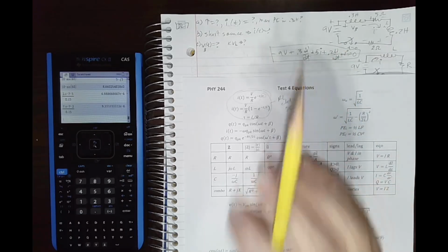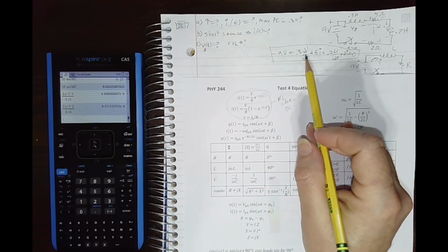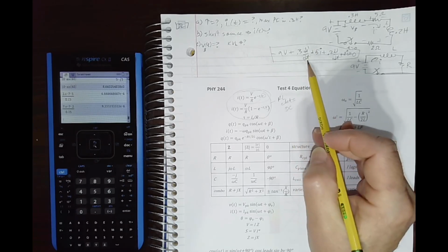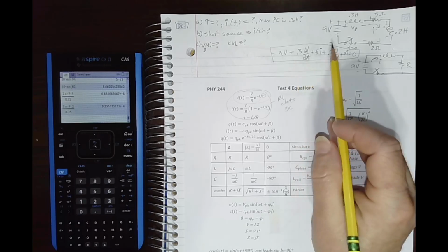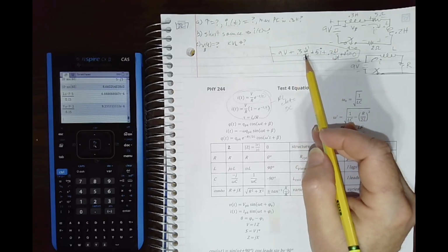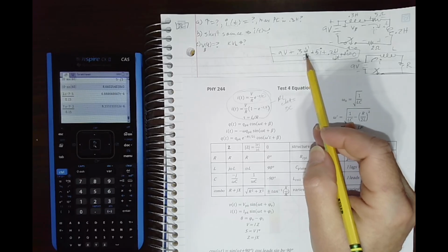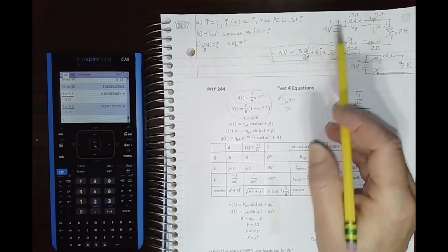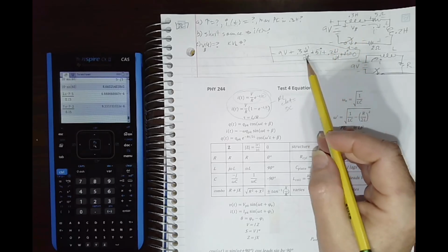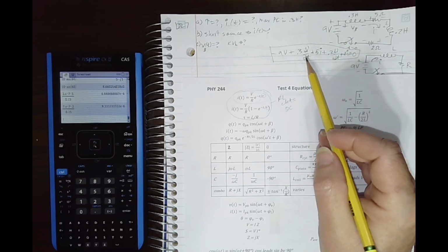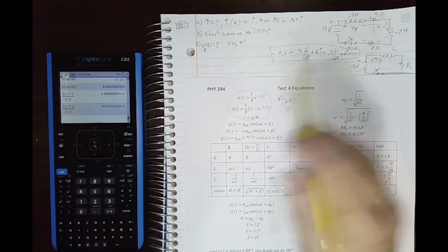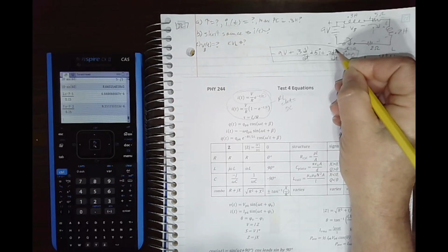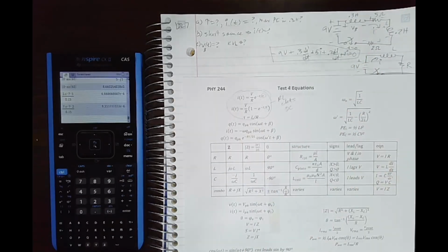It's not going to just jump instantaneously, because if it did, di/dt, a big change over a small time, gets huge, and we get a huge voltage, right? We can't get infinite voltage for sure, and so inductors limit the current, so it'll slowly let the current ramp up. And when the current reaches its maximum, it peaks out, and it levels out at a constant value.